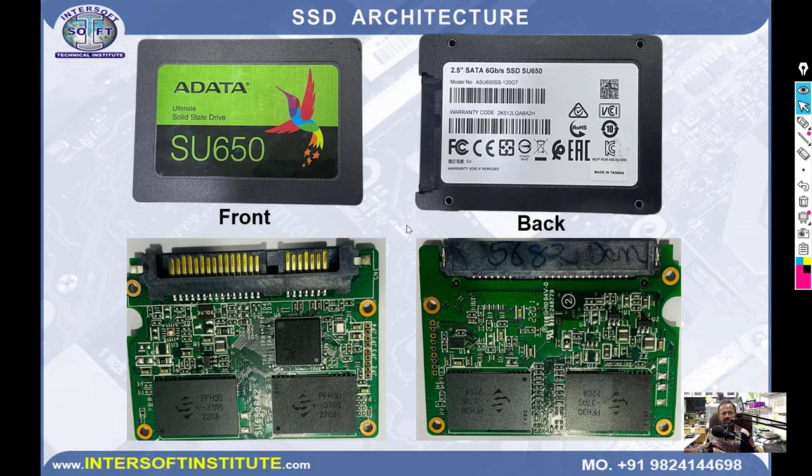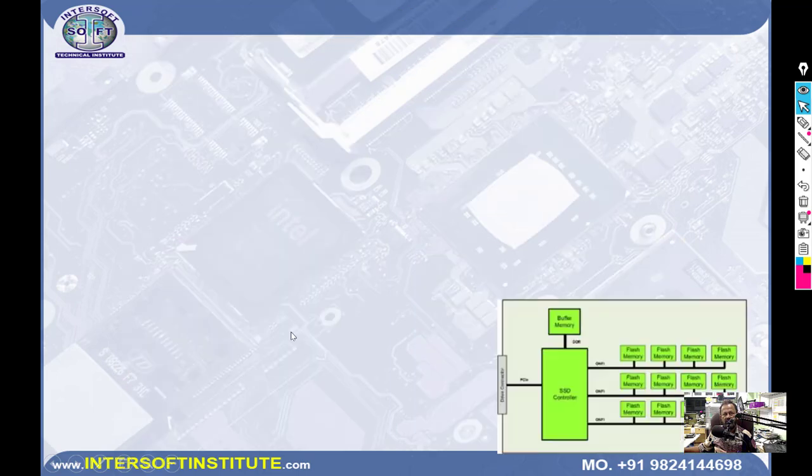When you open the SSD, it looks like this small one. Inside, half of it is occupied and it is light in weight, because it is a PCB with no moving parts. A hard disk is heavier. These are the SSDs, and they have a power connection and SATA connection. Here you can see the controller, two or four or one ICs, one crystal, and the switching section. Power related issues are there.